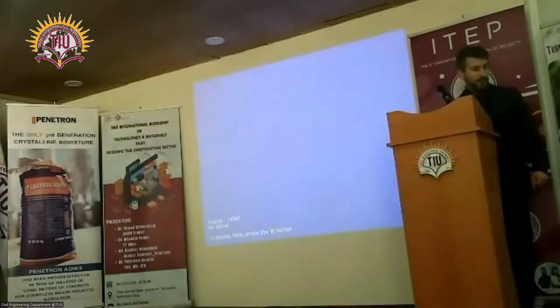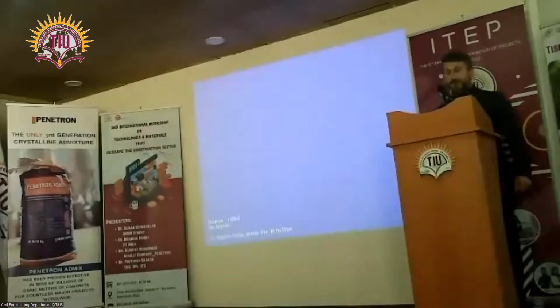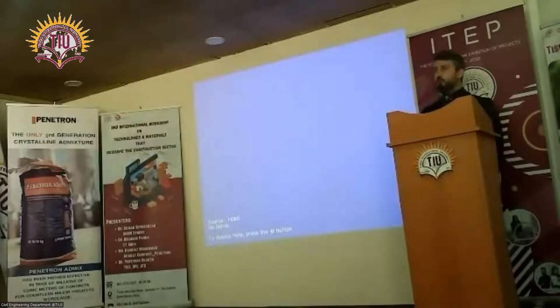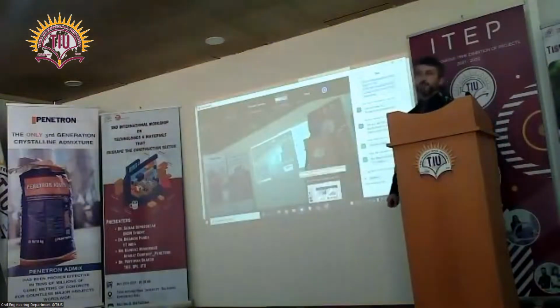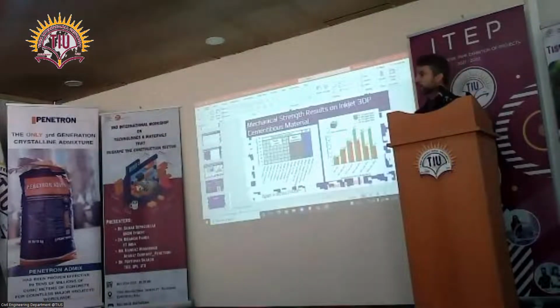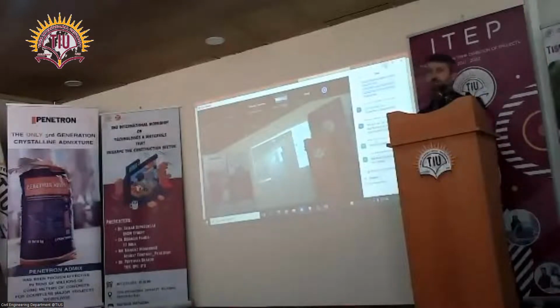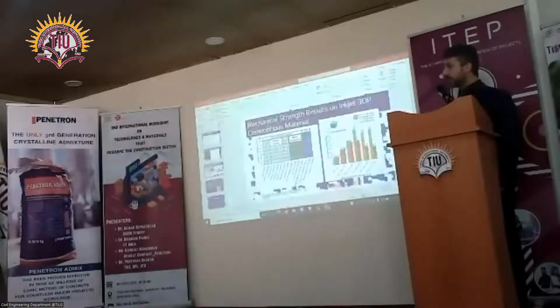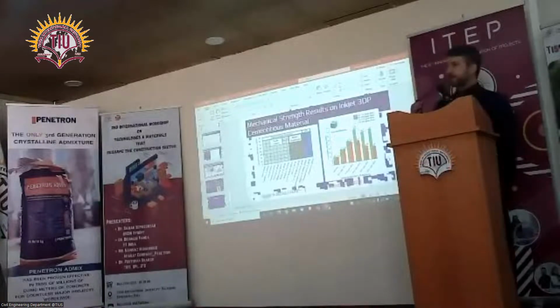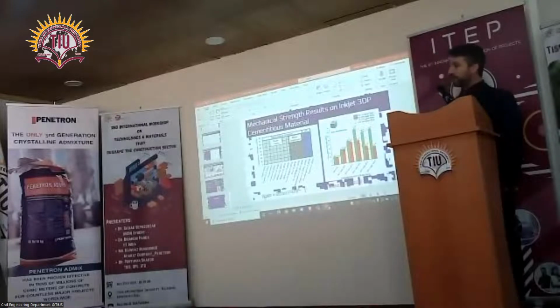Right. Many studies have been done on shear walls and retaining walls, especially by Professor Kloff in Germany. Now he is working not only on 3D printing concrete, he is working on shotcrete 3D printing. He achieved very promising results, 10% higher than the normal shotcrete applied by a nozzleman.